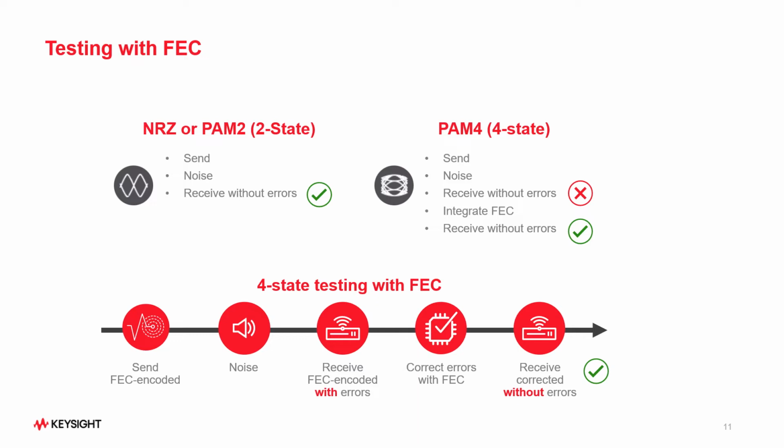However, like I mentioned earlier, PAM4 designs are far more susceptible to noise since an amplitude swing of 2 represents 4 signal levels. As a result, the SNR or signal to noise ratio is lower, and analyzing noise in transceiver designs becomes a very critical factor.